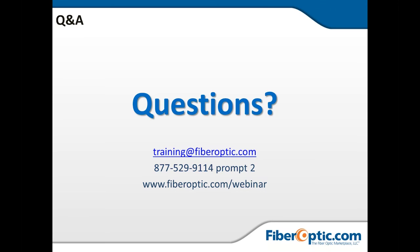I'm allowed to have .5 in each connector. So, if I've got more than a couple of dB in that patch cord, I'd be looking for a new patch cord. I'm hoping that answers that question for Mr. Latonia. I hope I pronounced that correctly.